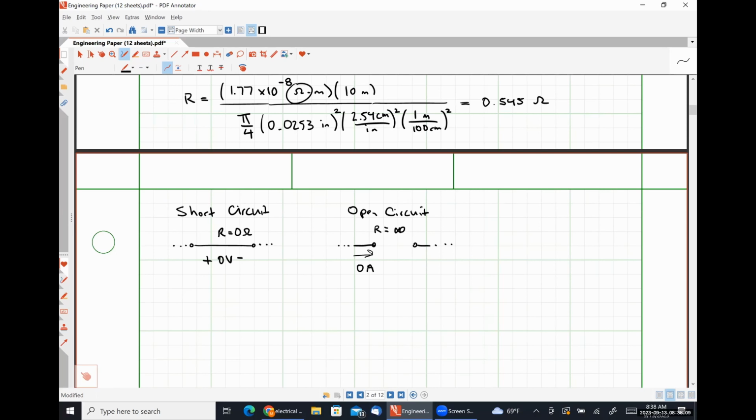A wire has some amount of resistance. We calculated it, very, very small. An open circuit also has some amount of resistance, very large, and it's typically associated with the dielectric breakdown voltage, meaning how much voltage per unit meter you have to apply across a gap to cause the air or whatever medium is between the two open terminals to literally break down and start conducting energy, right? If I were to take a plug and not quite plug it in, so that there's just a very, very small gap between the prongs of the plug and this receptacle, we'd start seeing a bunch of sparks and all of that kind of stuff, because the distance is one of the determining factors for when you're going to hit dielectric breakdown, right?